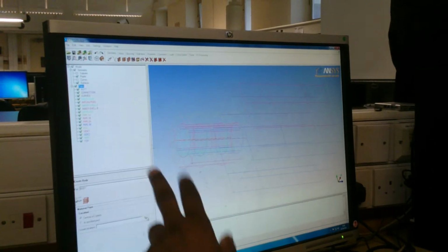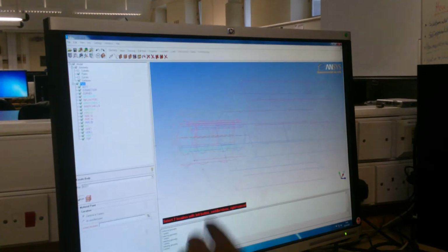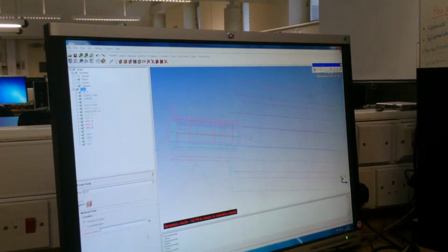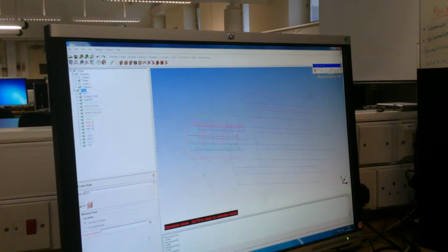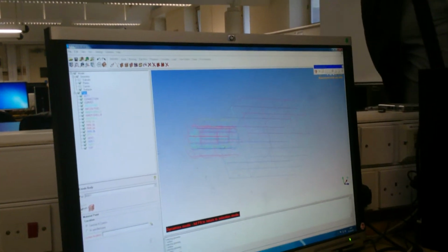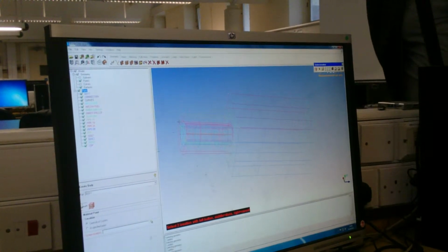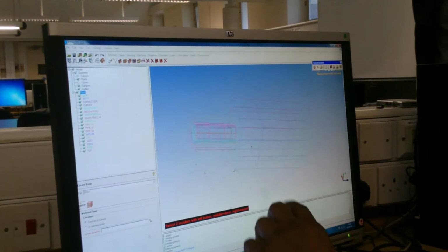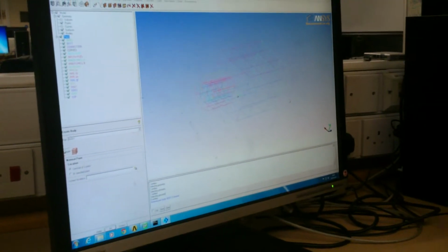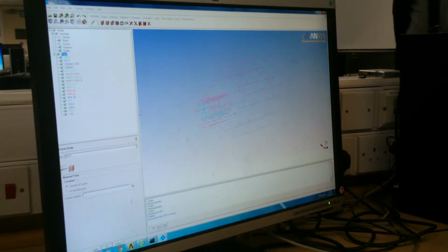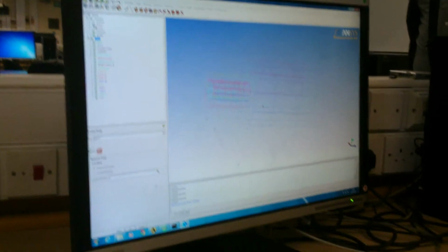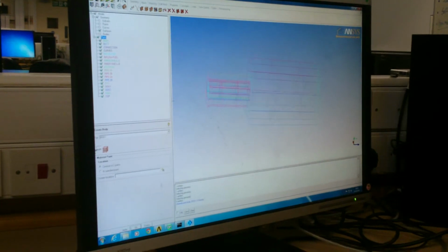Body between 2 points. Take 2 diagonal points, far ends. So I will select this point here. I will select this point here. I want 2 diagonal points. So if I select these points and I select these points, the body will be created here. Now the body connects all the geometry, making it one body to deal with as one body. Now here we are. We have finished part 1 of the problem. Put the points off. Put the bodies off. We don't need them at the moment.